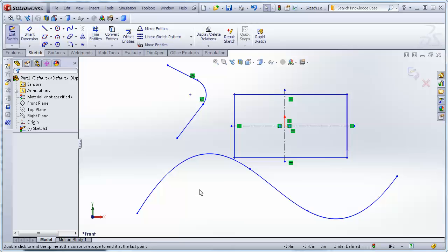Okay, this particular spline, if you look at it, just for reference, is called a natural spline, and it's probably a cubic spline, and if we were to take a thin flexible beam and force it to pass through all of these points, this is almost certainly the shape that a thin flexible wire or beam would take, including approaching a straight line at this end and approaching a curvature of infinity, a radius of curvature of infinity, a curvature of 0, or it's approaching a very straight line at this end.